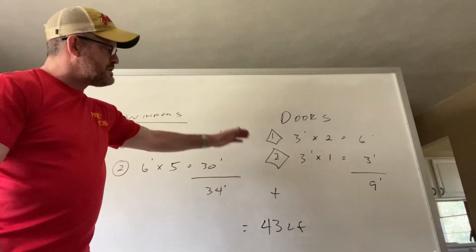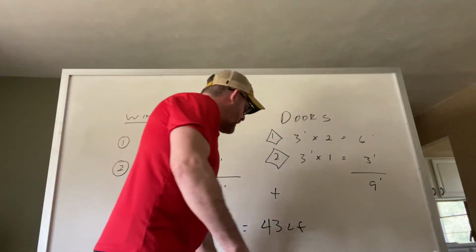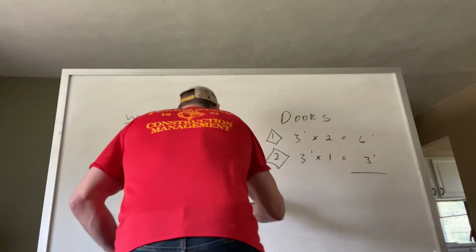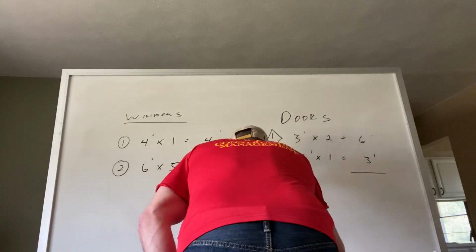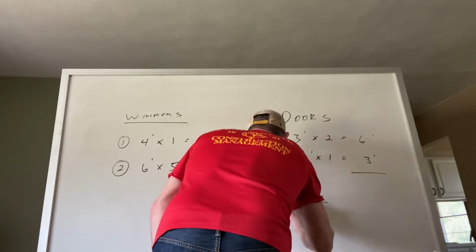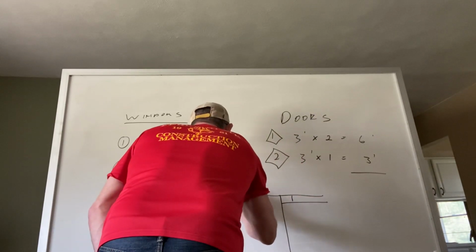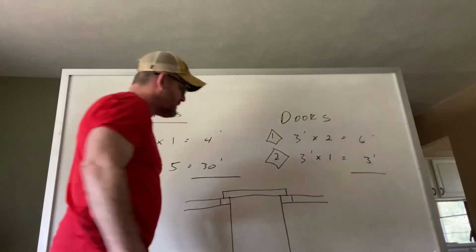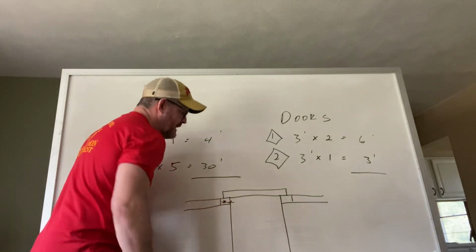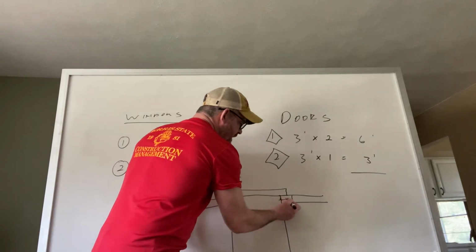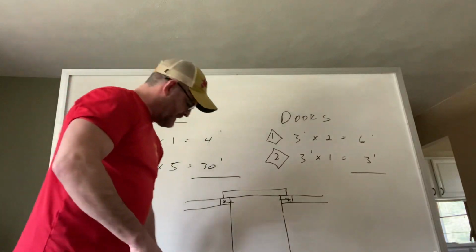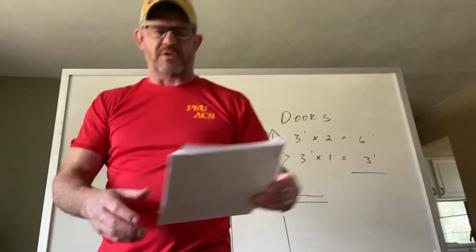I walked you through the same steps as we just did with the last one, but understanding my lintel, I have to take another step. Going back to how a lintel works, if I have this opening, and I know that my block takes me across my opening, what do I have to think about? I have to think about that lintel having to extend beyond my opening. I need to know what that dimension is. Again, is that something I'm going to determine? No. I don't have PE behind my name. The design team is going to determine that.